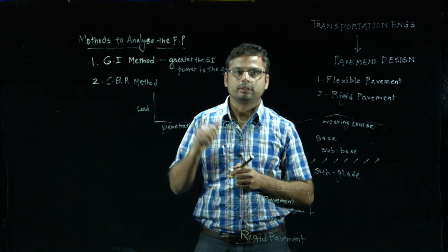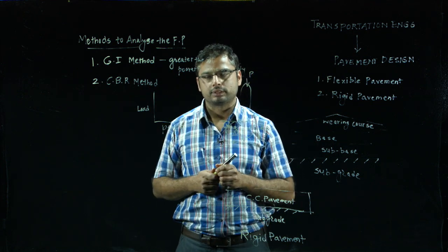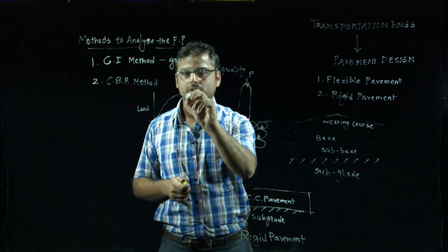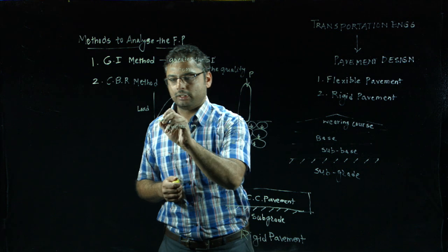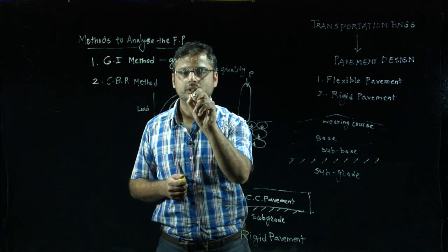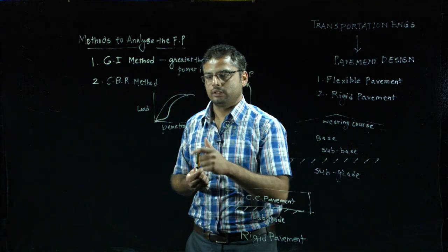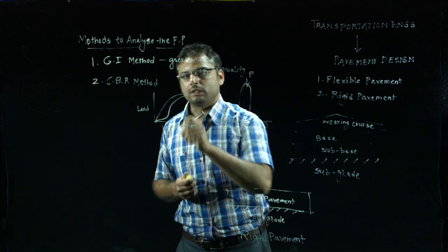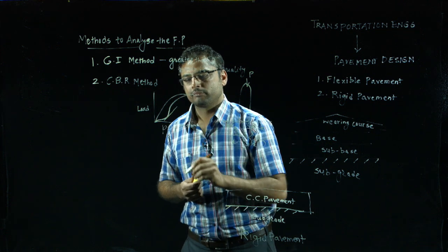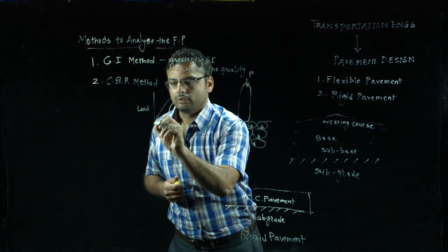We will plot the results between load and penetration, load being on the y-axis and penetration on the x-axis. Basically we should get a curve like this, but sometimes there is a concavity downwards in this curve, which means there will be a correction in this method. The correction applied is simply to draw a tangent from this concavity and extend it onto the x-axis, then measure